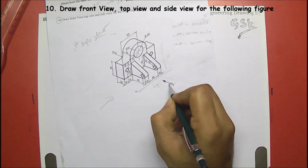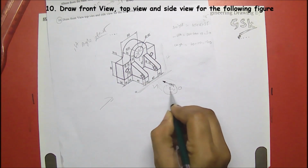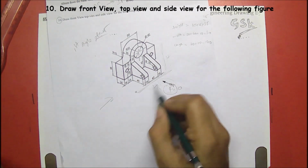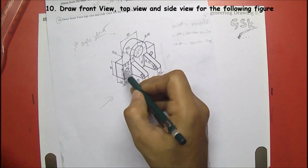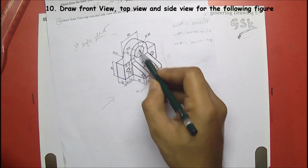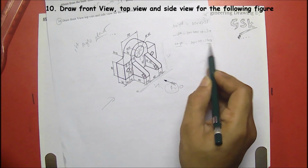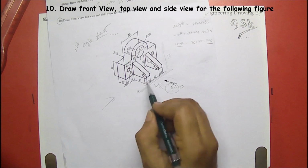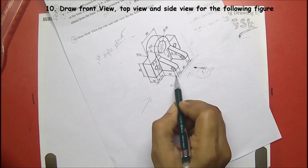So in this direction, this is the arrow mark, this is the observer, the front view observer. Here I can see the length and height. For the length, I'll be taking this one total 70, exactly at the half point, and there would be 70. So the total length would be 140. Coming to the width, this is 30, this is 40, and this one would be 10.